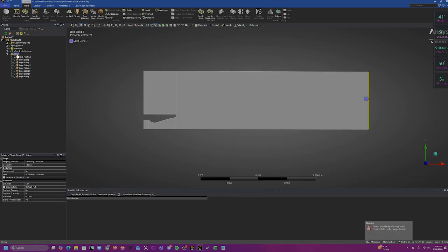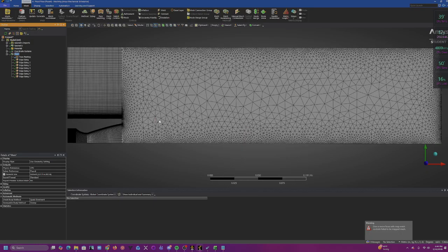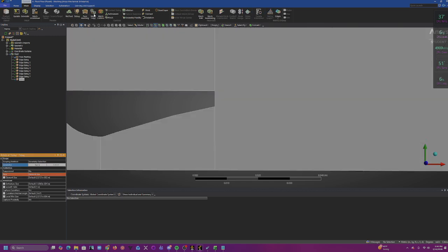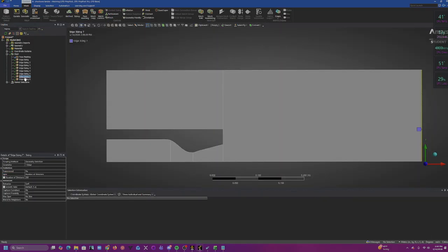Okay. All right, cool. So we're gonna add our last sizing at this section right here. Make sure this right here is green, and then we can click apply, element size, number of divisions, and this number of divisions, I believe, let me see what it was. So 100 divisions and a bias factor of 100, right?